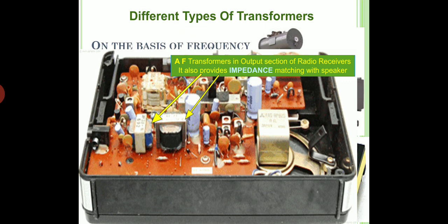amplifier base, and again from the output you need one more transformer to connect the load. So the output collectors are coupled or biased through a transformer, and the secondary of the transformer will be collecting the amplified audio signal, which in turn is connected to the loudspeaker in a radio receiver. That's the reason why here you have two transformers.